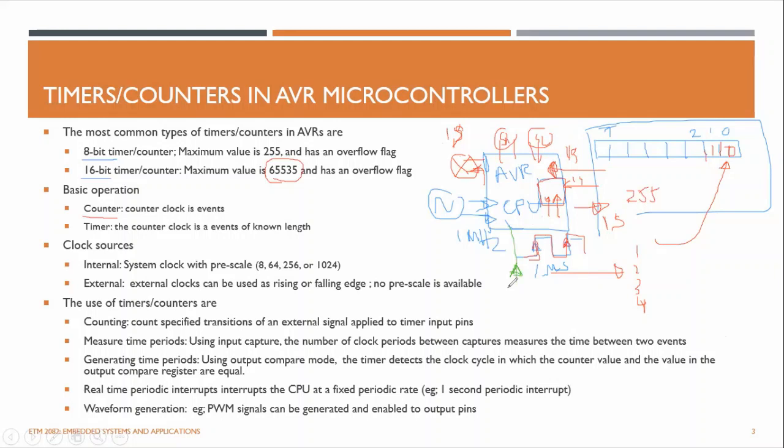If you take this pin, the counter pin, for example, now we have some sort of encoder. The encoder is generating this kind of pulse for a motor application. So when the motor is rotating, the encoder's pulses will be like that. To go one revolution, let's say this motor takes 10 pulses. So you can couple this encoder to this pin.